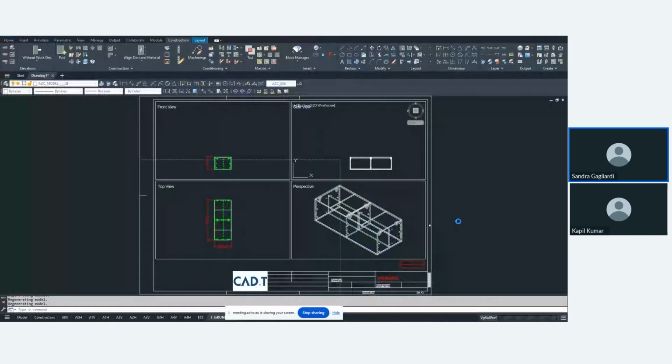Plus, additionally, we have our CAM interface when you send the drawing there, which analyzes the material, the logics of the machine, the geometry, and your tools as well, and makes sure that all the machinings are correct and that there are no collisions. It will also show you a preview. I hope this answers the question.